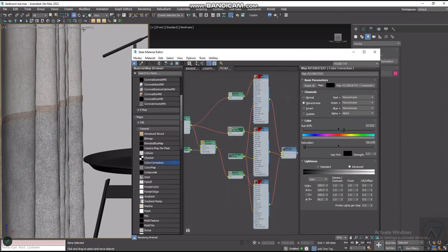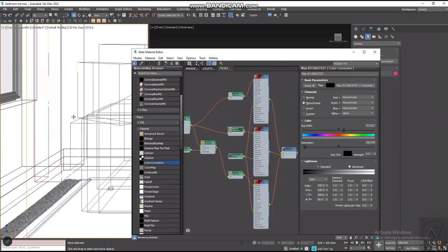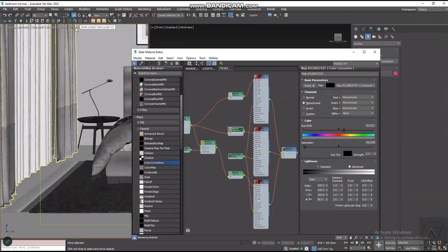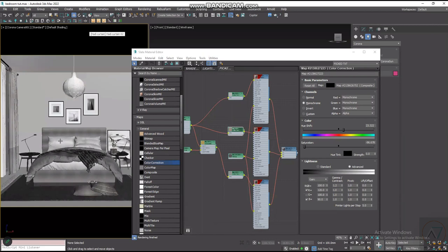You can exit this 2D pan zoom now. You can see we are still zooming. So to exit it, just click on this. You can see now 2D pan zoom. Click on it and exit. So it's back to normal now.